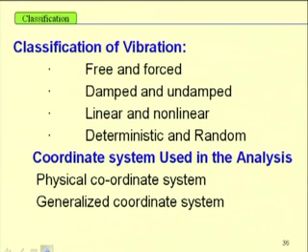Again, this free vibration can be divided into three different categories. Depending on the damping, it may be under damped, critically damped, or over damped. In case of forced vibration, depending on the nature of the force, we can have different types of response. While free vibration gives rise to a transient response which dies due to the presence of damping, in forced vibration the system will oscillate with different amplitude and frequency depending on the nature of the force.